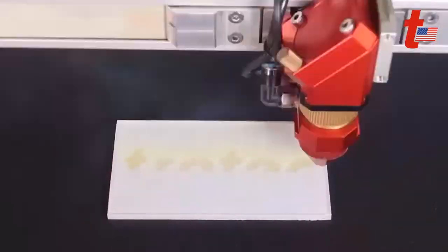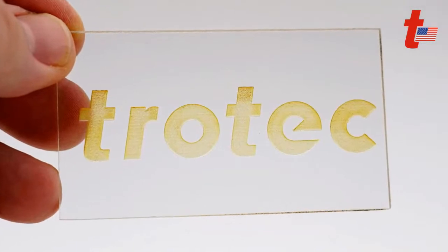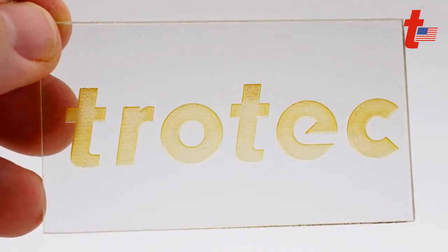So this is the CO2 laser engraving onto the surface of it. I've left the masking on the back side. You just engrave it, and then peel it off, wipe the surface of any excess residue, and then you get that nice yellowed finished result. Not much more to it. Again, I don't recommend barcoding or anything like that, but if you just need to put a serial number or something onto it in a corner, the small characters are going to be legible. They're going to be readable, but again, it's not going to really pop out like the black that you would like to see. And that's where the fiber laser comes in.